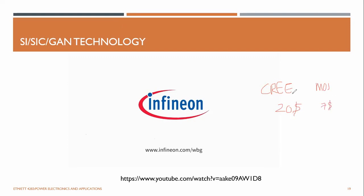So the silicon carbide devices are more expensive compared to typical MOSFETs, but they have superior characteristics for our application because we had to deal with voltage over around 1,200 volts and current up to 35 amperes. That's why we went with silicon carbide devices rather than using just silicon.